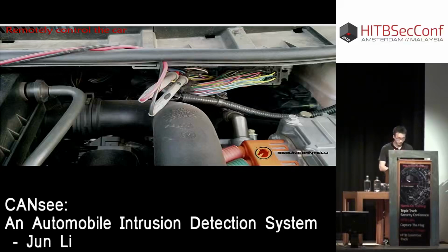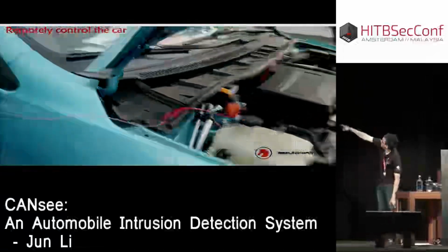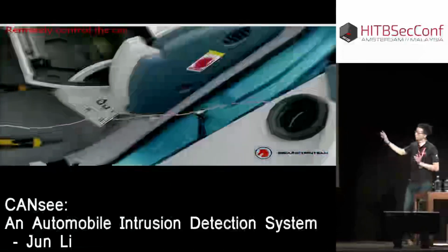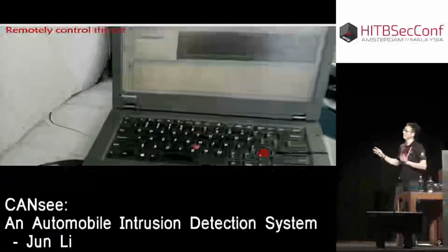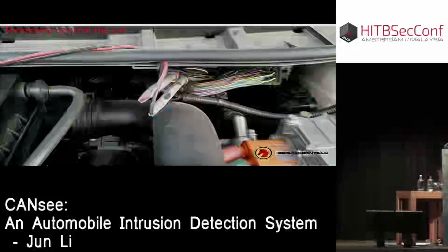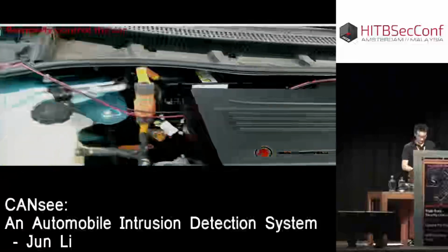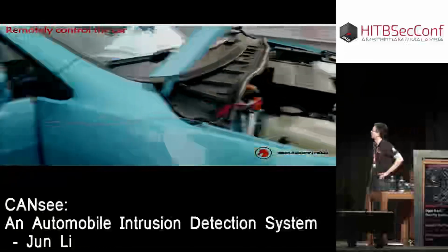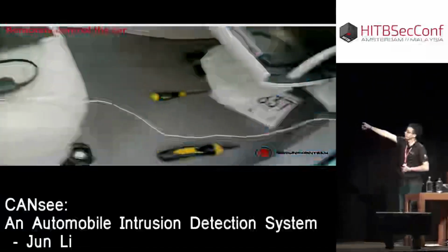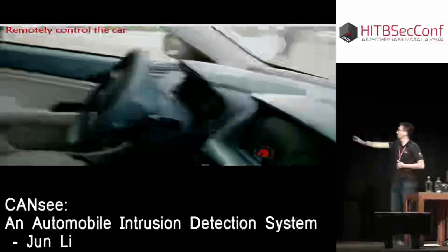Okay, let me show you the cyber-physical side. I mentioned that I'm currently collecting data from the engine control CAN bus. This video is just to show you that this car has the X-by-wire system. You just use two twisted wires to connect to the CAN bus, and using a CAN interface and the software, you can collect the CAN data.